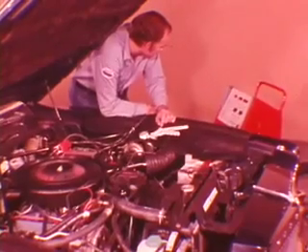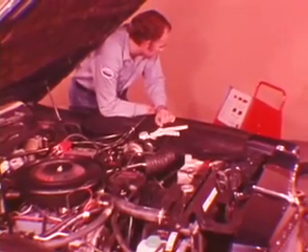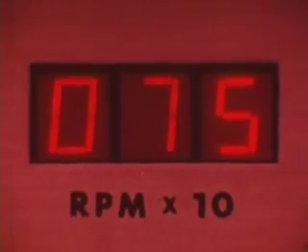You should see code 99 flashing, indicating a test in progress. This will continue for about 90 seconds. During this time, the analyzer will simulate many different operating conditions and check the performance of the spark control computer under those conditions. You can watch the simulated engine speed changes on the analyzer.